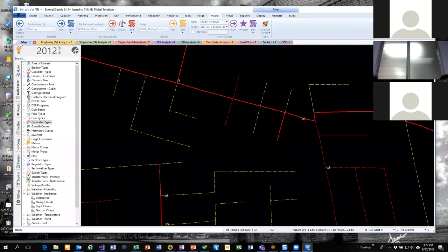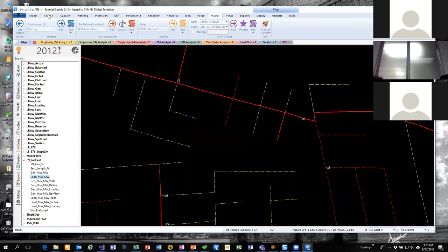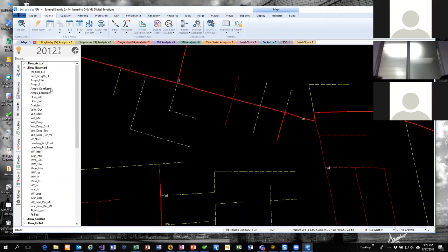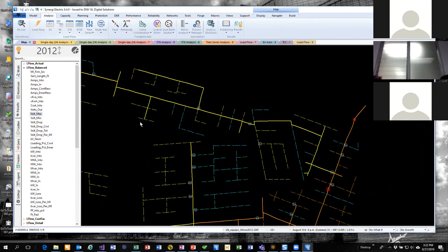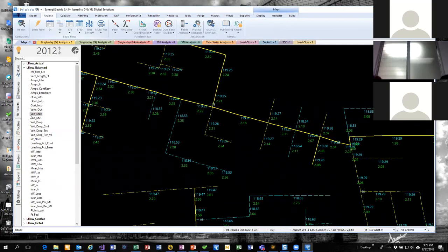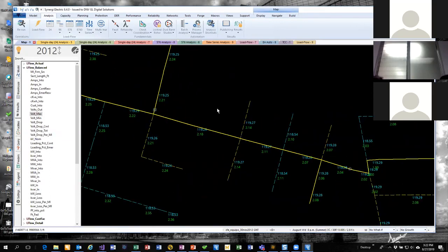The use of Excel is all over the place in Synergi now. And if I go in here, I just run a load flow. And if we wanted to look at something like our balanced results here, we can click on this once and color the map. We could right click on this and show annotation. So we can put the maximum voltage on the map as annotation.